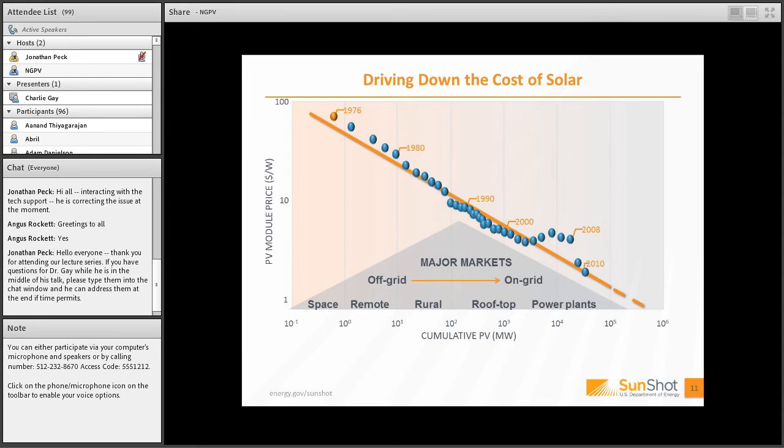And by 1980, we had a grand celebration at the end of the year because we managed to produce 1 megawatt in that year. Today, most fabs run producing a megawatt before lunch. So the scaling has really taken off, but it's still that same screen-printed contact system and pretty much the same packaging system of tempered glass front, ethylene vinyl acetate, and a fluorinated polymer like Tedlar as a backsheet on the module.